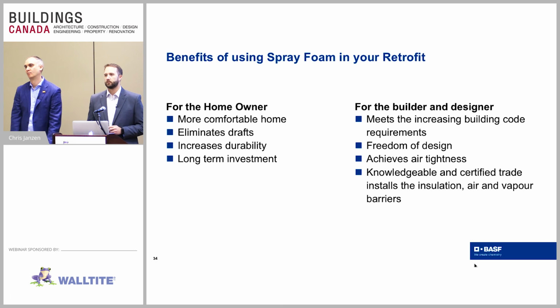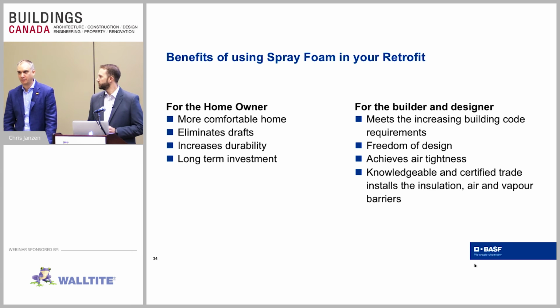If you're going to use spray foam between the studs, how do you account for vapor permeability right through a stud? The stud itself is a vapor barrier. They're less than 60 nanograms as well. Okay, so there's continuity there. Basically it's just the cracks. For vapor permeance, you're not too concerned about the joints between the wood studs. It's more from an air leakage standpoint. You want to make sure those joints are addressed.